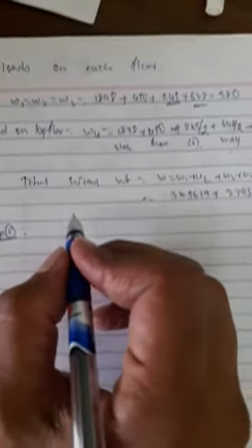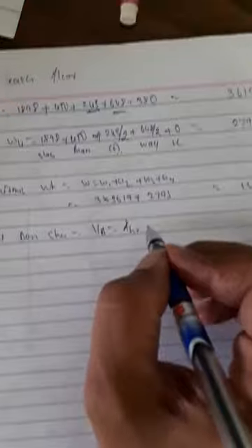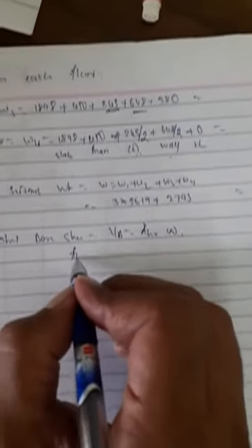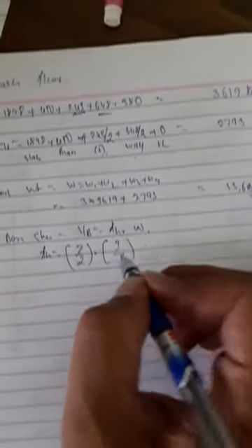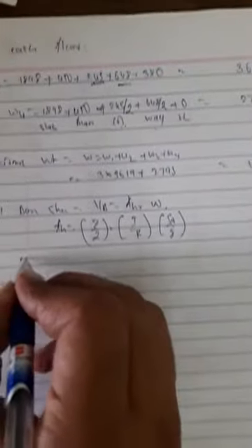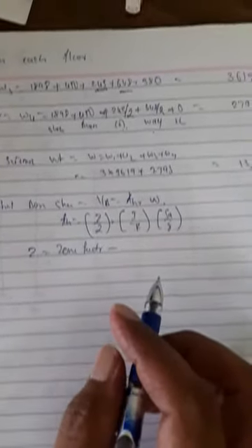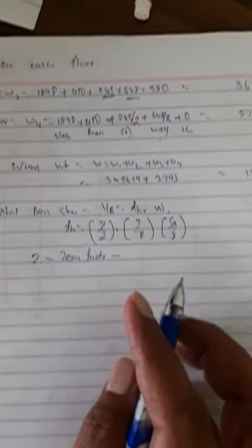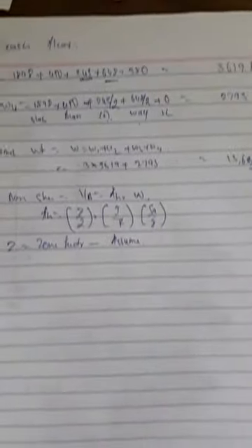Next, step 2, base shear. Total base shear VB is equal to AH into W, and AH is equal to Z by 2 into I by R into SA by G. Next, Z, zone factor. For zone factor nothing is given, so you can assume Z is equal to, one second, is that given?